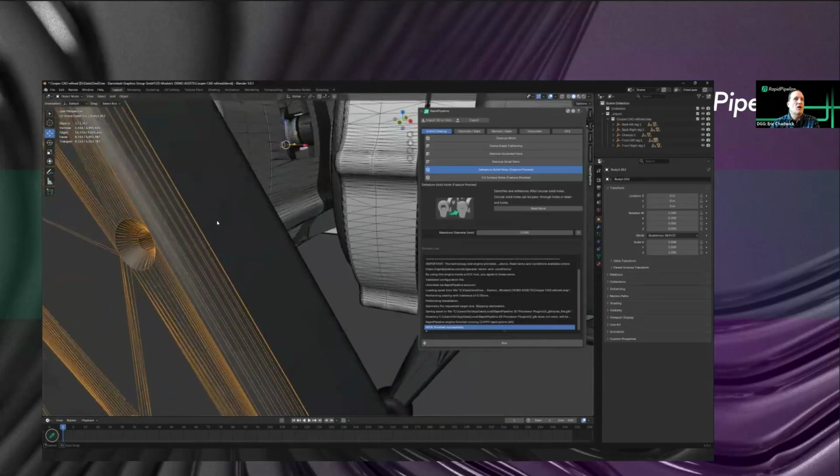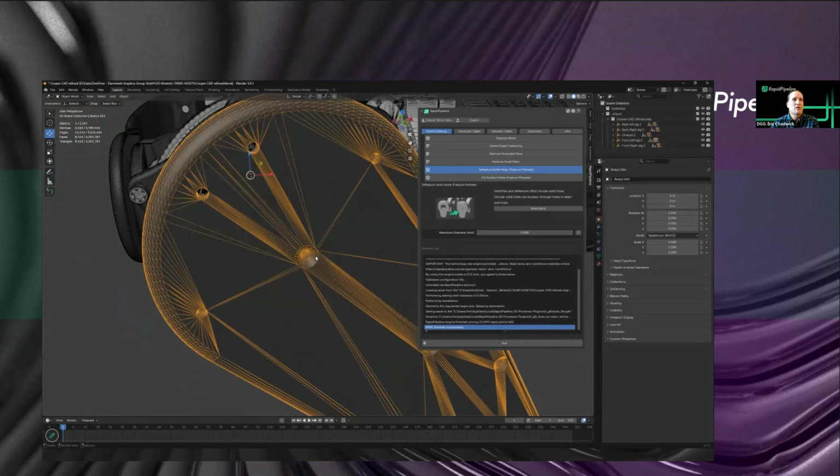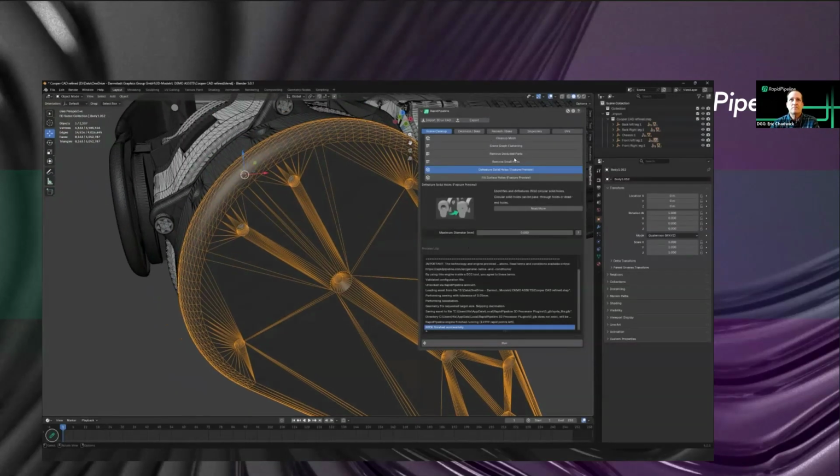And it basically will cull all those out because it sees that this is a perfectly round hole with an entry and an exit. So you can say, how big do I want this to be in millimeters before it removes it? And I think this thing is maybe a centimeter across. Maybe it's a little bit less.